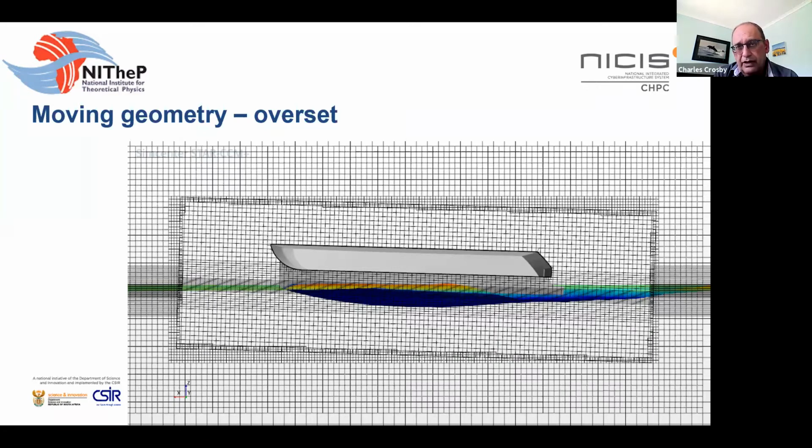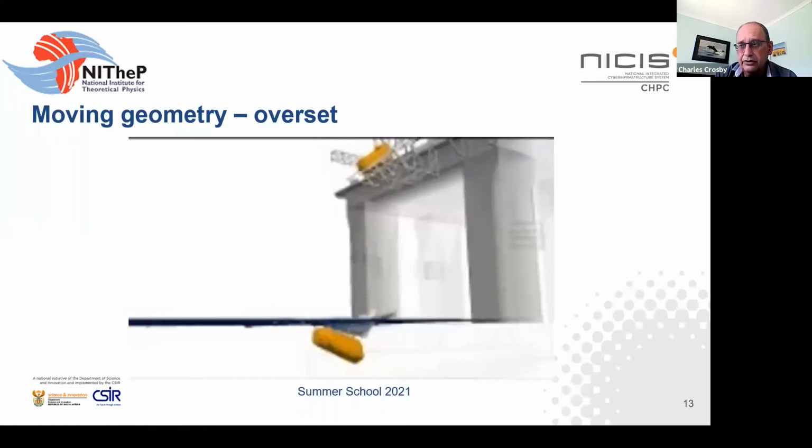So you'd have a helicopter airframe, and then you'd have all the different things that they were going to hang under the helicopter. Each of them would be meshed at very high resolution and very accurate with a very smooth, high quality mesh. And then they would just combine them as they needed. The method would resolve the whole question of cutting out holes and two different meshes overlapping with each other. It gave them a very sophisticated and very accurate method of developing solutions for regions with arbitrary motion and arbitrary complex geometry. So it's an interesting approach, and it's become quite popular again, as it's now been combined with unstructured meshes. It has the advantage that it allows for very large relative motions.